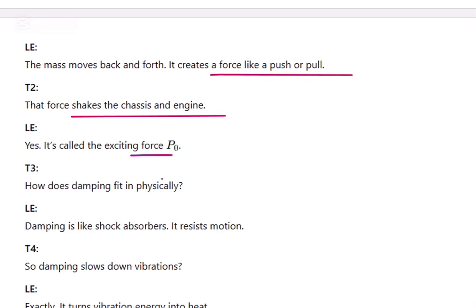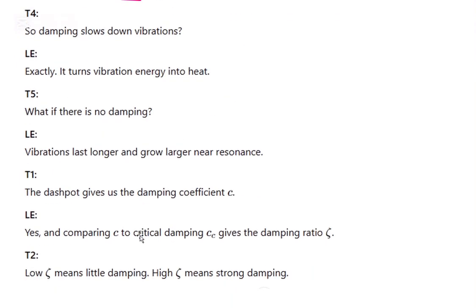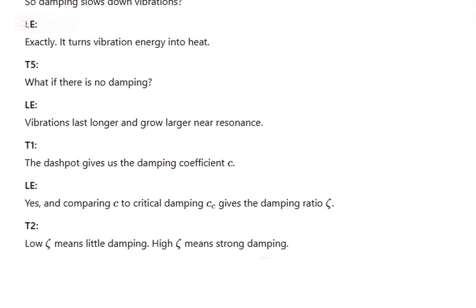How does the damping fit in physically? Damping is like shock absorbers. It resists motion. The damping slows the vibrations. Yes, that's right, because damping turns vibration energy into heat. What if there is no damping? Vibrations last longer and grow larger near resonance.